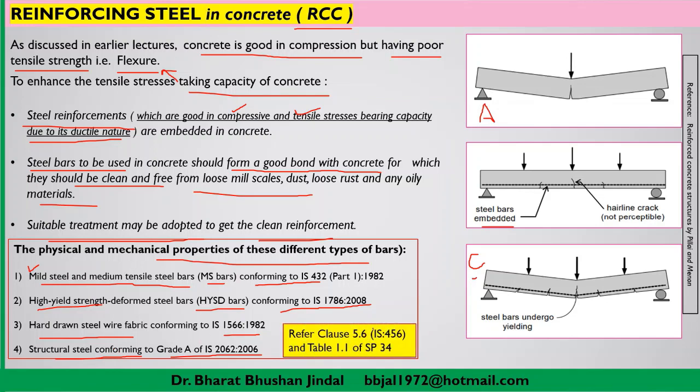For more detail you can refer to clause number 5.6 of IS 456, and you can refer to special publication SP 34, where table 1.1 gives all the related and important information regarding the steel bars which you can use as a reinforcing material in RCC structures.